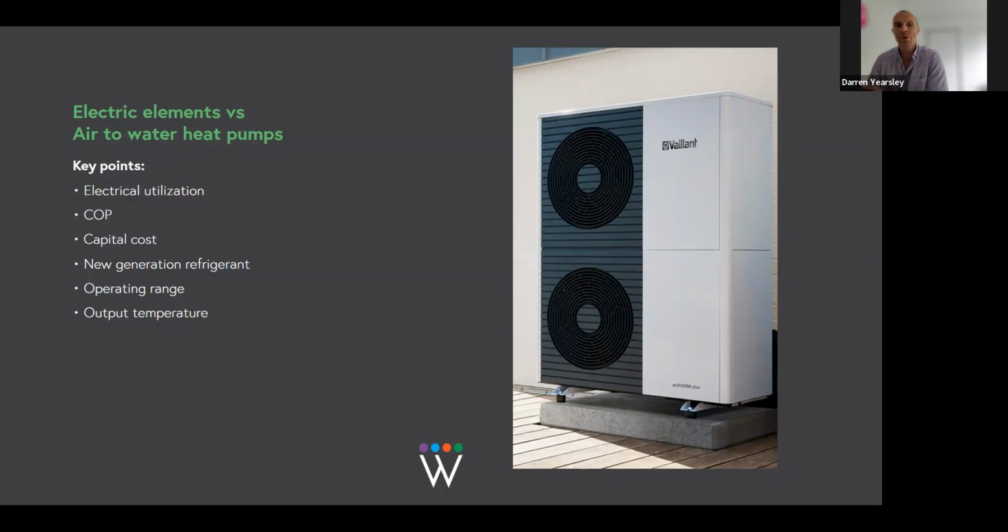Then as you add apartments, it gets proportionally cheaper and cheaper and cheaper. With an air-to-water heat pump system, typically the break-even is a little bit more expensive. The heat pumps are more expensive per kilowatt than a gas boiler system is. So the break-even for an apartment is about 40 apartments. So 40 electric hot water cylinders costs about the same capital cost as what a centralized air-to-water heat pump system costs.